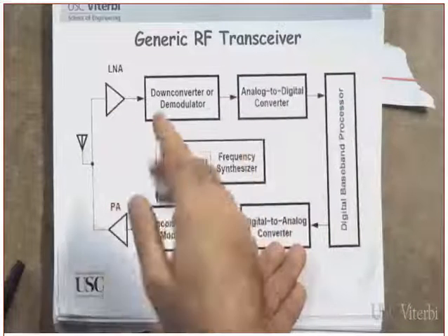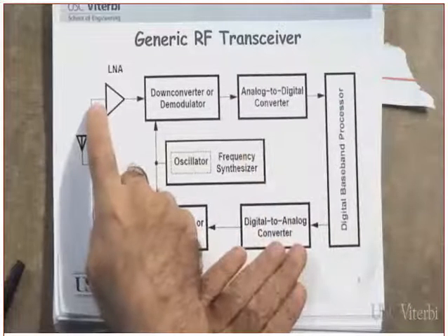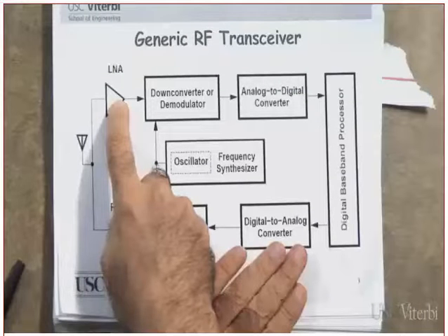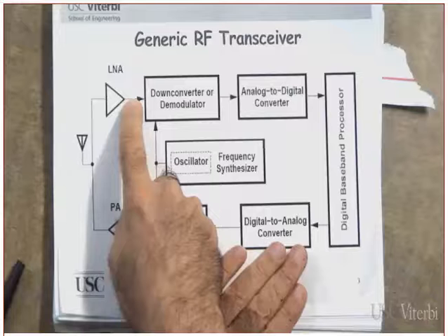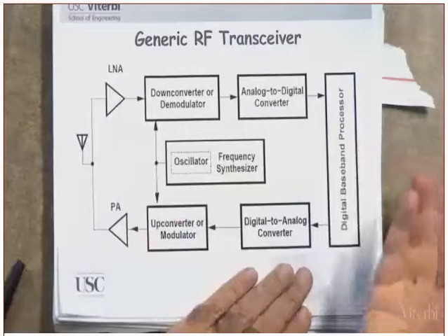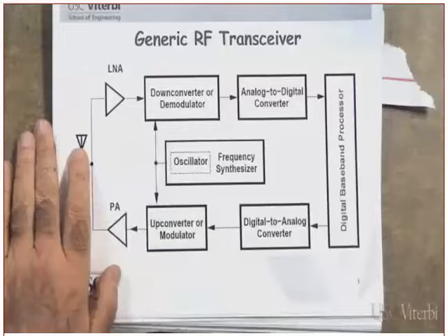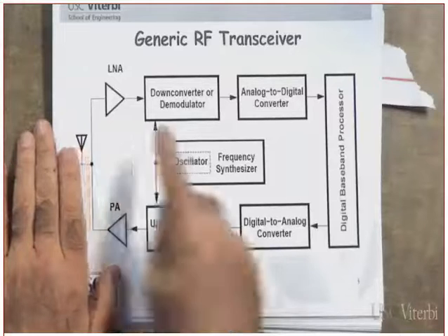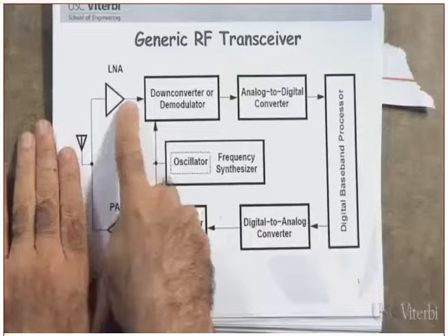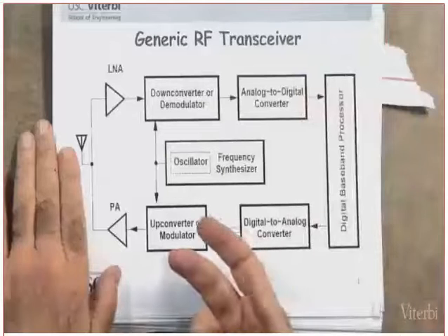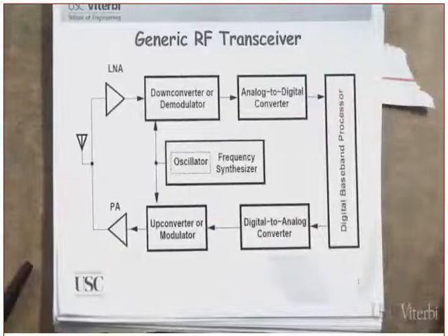Now let's assume, forget about dB, let's make things simple. Let's assume the signal to noise ratio here is 5. If you use an amplifier with gain of 2, what should the signal to noise ratio here be? Why double? You are amplifying both the noise and the signal. So if the ratio here is 5, the ratio in here should also be 5. They found it to be lower than 5. Something must have happened.